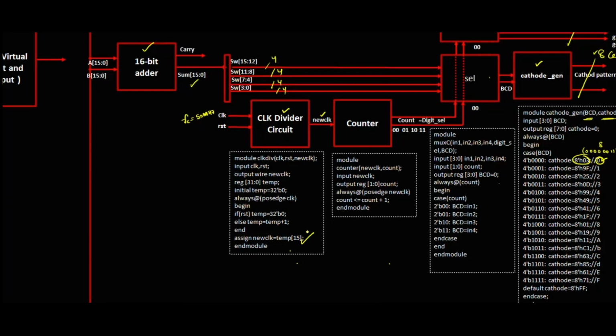What I need is a frequency matching the snap time, in terms of hertz. I will convert that high frequency to a low frequency using the clock divider circuit. So I will design a counter circuit, a module with the 15 combinations, and with it design a new clock.